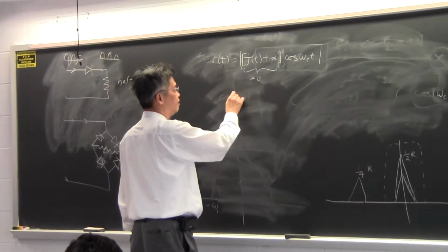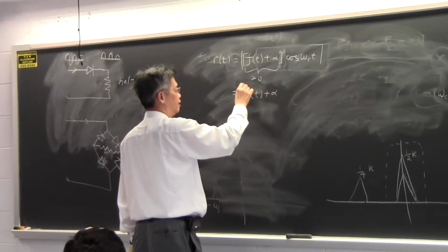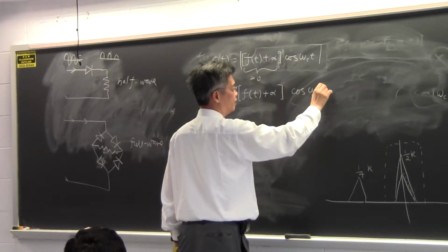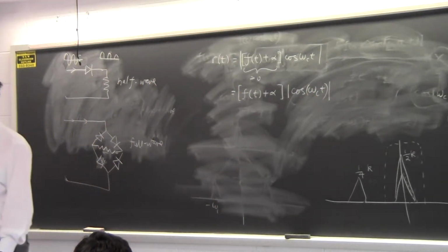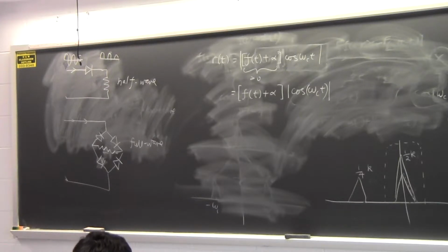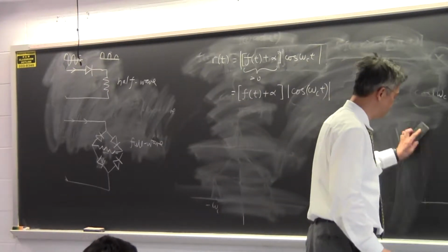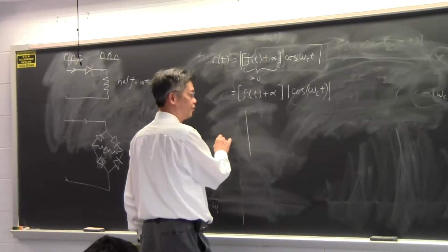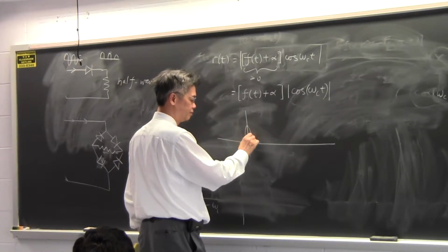So that you will take the magnitude of two signals, I can leave the first term the way it is without having to put a magnitude sign over it. Then I only need to put the magnitude sign over the second term. Then I analyze the Fourier spectrum of the second term in terms of Fourier harmonics. The second term, if I look at what it looks like, is just a cosine omega with everything turned positive.